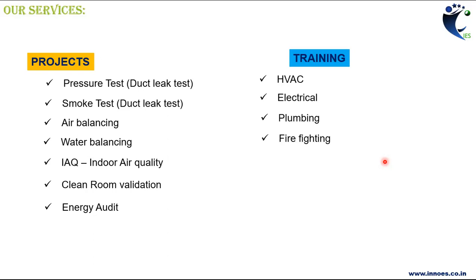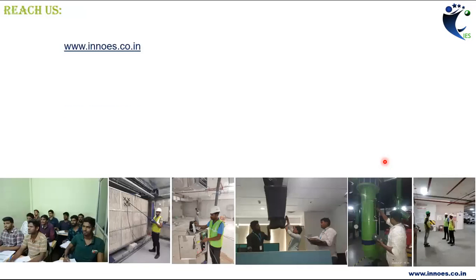The water is flowing inside the tube. That means if you are selecting a water cooled chiller, what will happen? Salt formation is happening inside the tube. So descaling is a very big cleaning process. Okay, that's why in that kind of area we are going to select the air cooled chiller.